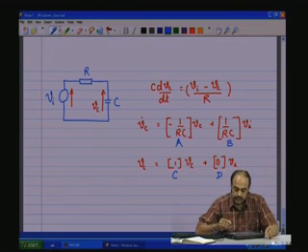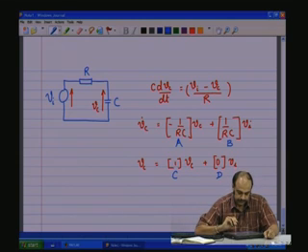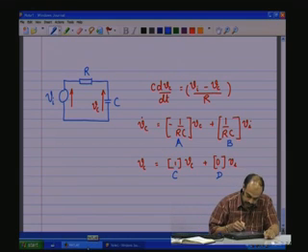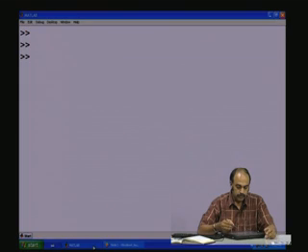So, what is necessary to be inputted to the software environment is the A matrix, B matrix, C matrix, D matrix and the values of the parameters R and C. If you go into this MATLAB computational environment, the command window looks like this. This is the MATLAB command window. This is where all the equations are typed in and the results are viewed.